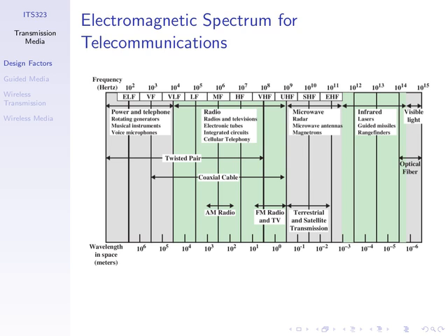So, we have this portion of the spectrum that we have available to transmit our signals. The other examples we see here, and what we're going to go through, are some of the wired transmission systems, which is the same principle. With twisted pair, we can transmit electrical signals up to a range of about 100 megahertz, 10 to the power of 8, or a bandwidth of about 100 megahertz. In fact, some even go up to 250, even 500 megahertz. Coaxial cable is another system with a slightly higher bandwidth. We see the bandwidth is the minimum frequency up to the maximum frequency.